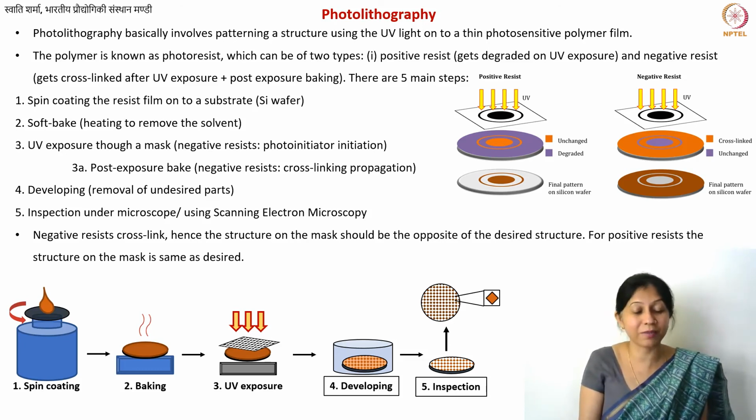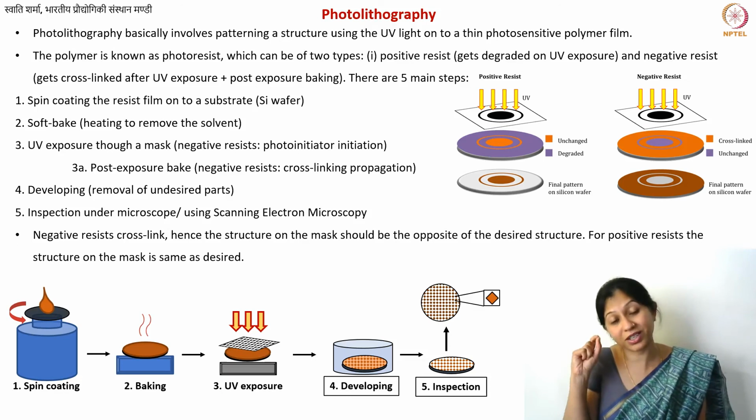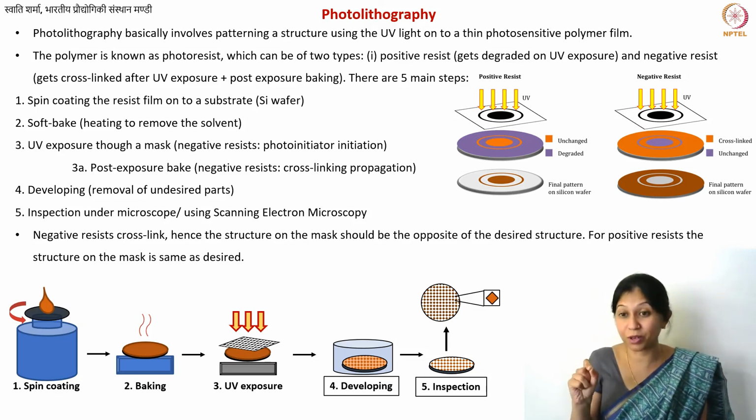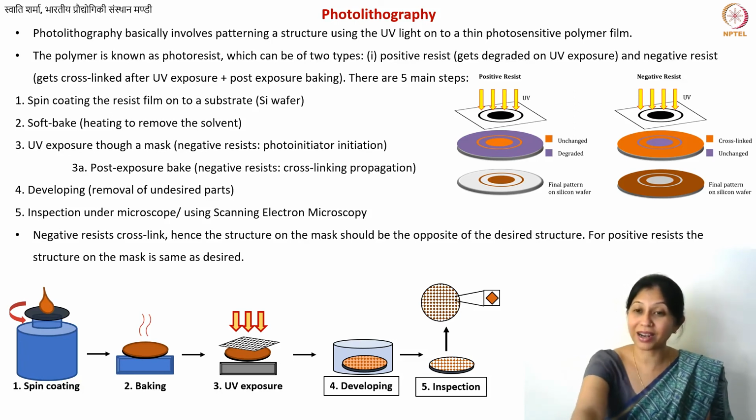You can even sometimes carbonize micro scale structures, and now you get nanoscale structures. So you did not really have to use a fabrication technique usable for nanoscale. You could just convert your micro scale structures into nano. So even that can be used as an advantage. The wastage of material is not that big a problem in the case of micro scale, because overall the usage of material is much less compared to what you have in the large scale structures.